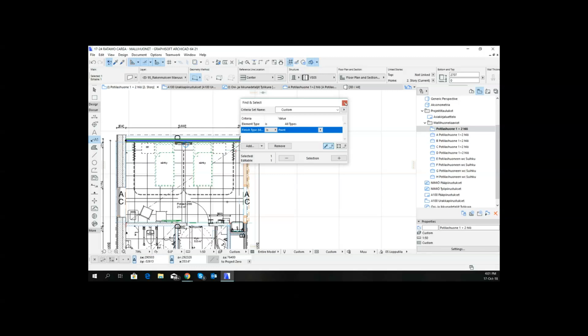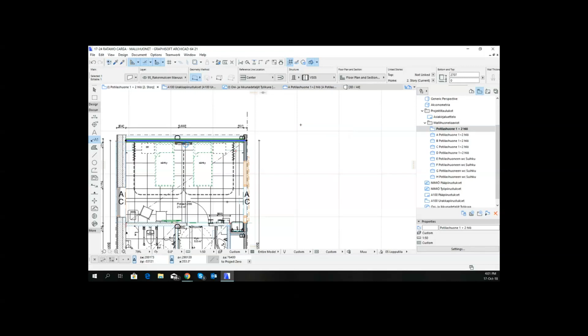If you were trying to calculate the sort of surface area of tiles or something, and you assigned it to a wall, would it sort of count the surface area of both sides? I think you would be able to do that by assigning different materials to different sides of the walls, one being tiles, one being whatever. And so then when you're saying calculate the surface area of the wall with this material on it, it will only calculate that one face.